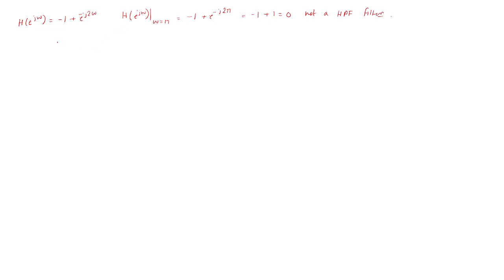Okay, so h[n] with odd symmetry and odd length, this property satisfies, it implies the filter is neither a low pass filter nor a high pass filter, but we need to check the other cases also.